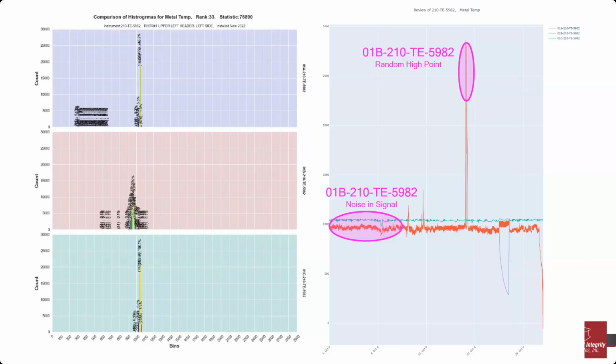Anything to add on that one, Kane? Yeah, the only thing I was going to say is that the other factor in terms of calculating damage on these is if it's an older unit, the material, for example Grade 91, is going to have not as tight of chemistry control. So you might have more creep-susceptible Type 1 material, as opposed to a newer unit where they're going to have done more additional hardness checks and tighter chemistry controls, such that hopefully you should end up with better creep-resistant material.